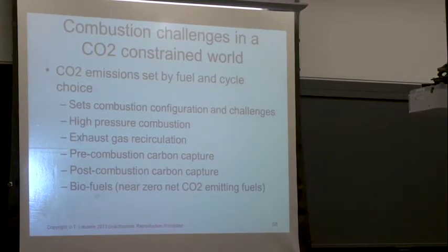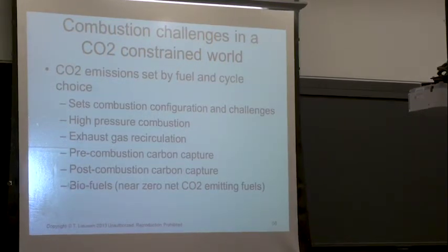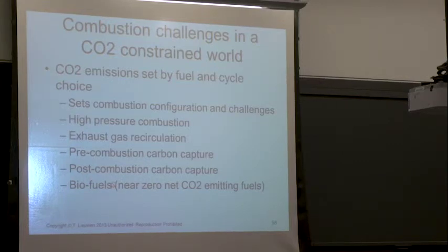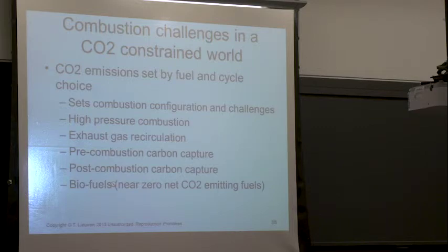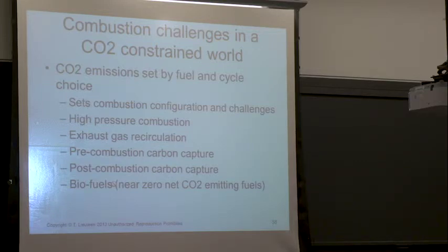Or biofuels, and this says biofuels, but this could also be synthetic fuels, because the idea is, suppose that you generate a hydrocarbon synthetically. It could be using a Fischer-Tropsch process. So, for example, if you take carbon monoxide and hydrogen and you run it through a catalyst and you generate a synthetic diesel or a synthetic kerosene, you know, this is already done.